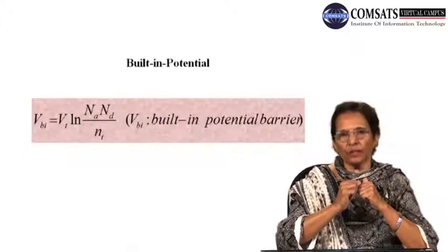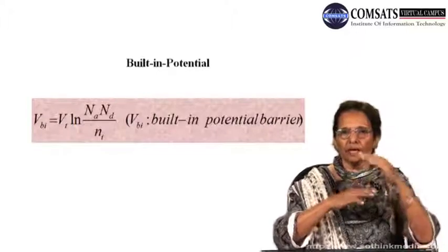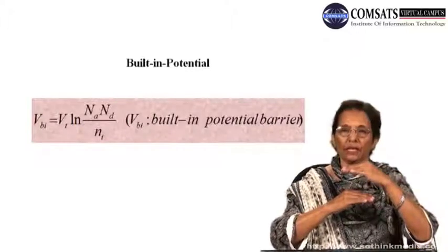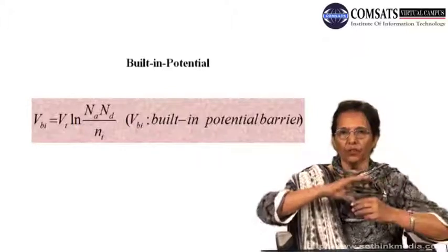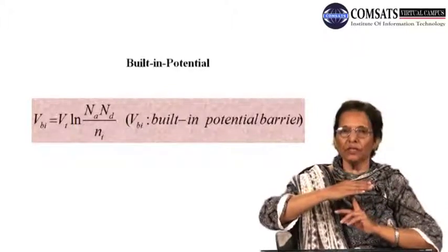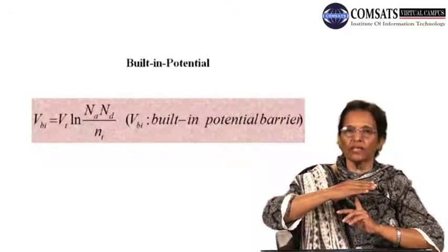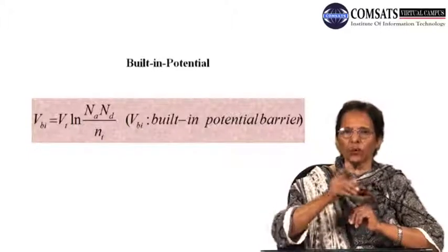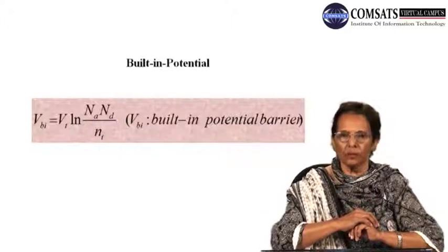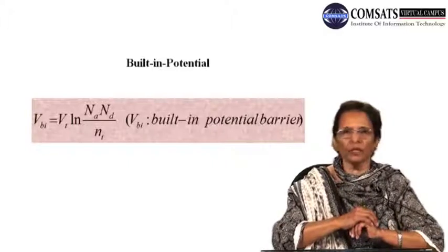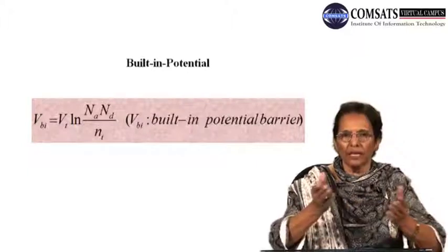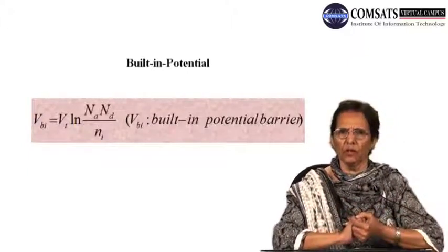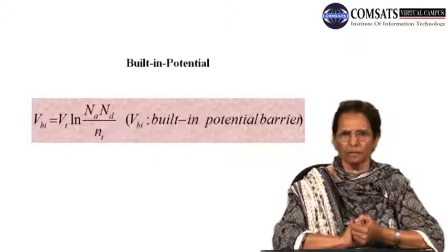In the intrinsic semiconductor materials, there are obviously free electrons in the conduction band, and free holes in the valence band, even in the intrinsic, that is pure semiconductor material. Of course, this is at room temperature, 300 Kelvin, because at 0 Kelvin there would be no free electrons and no free holes, hence the material would behave almost like an insulator.